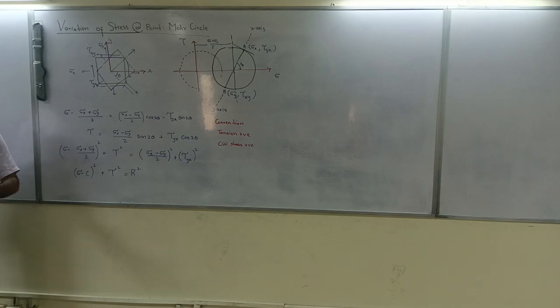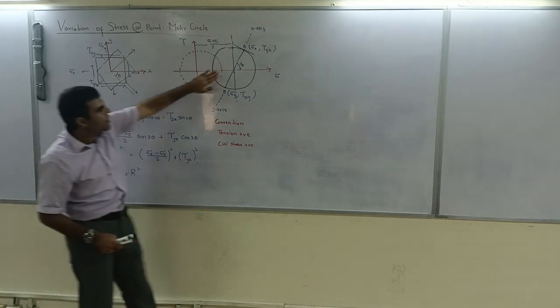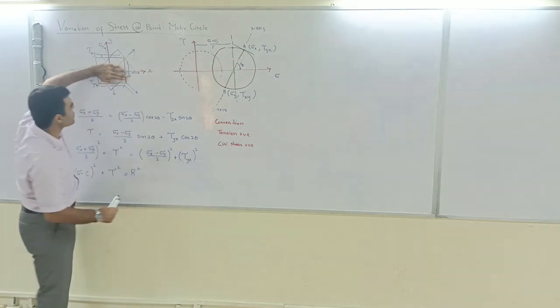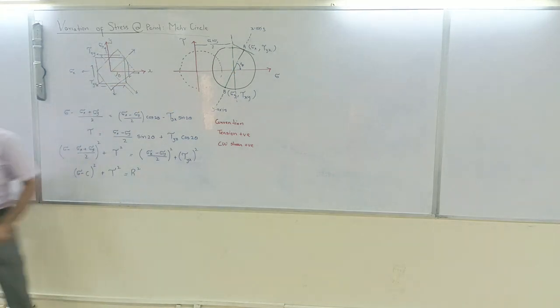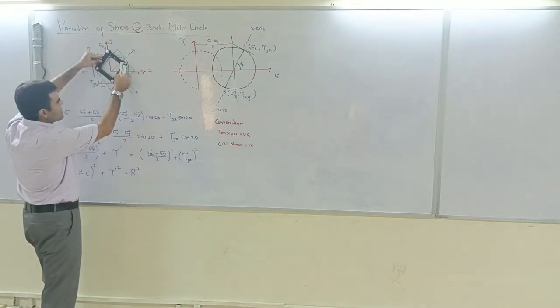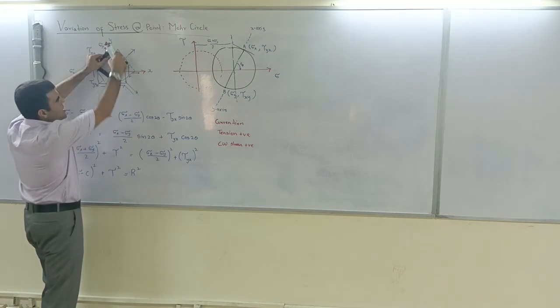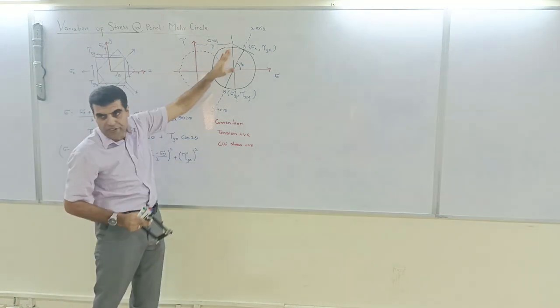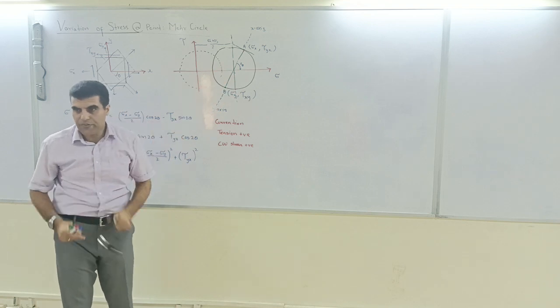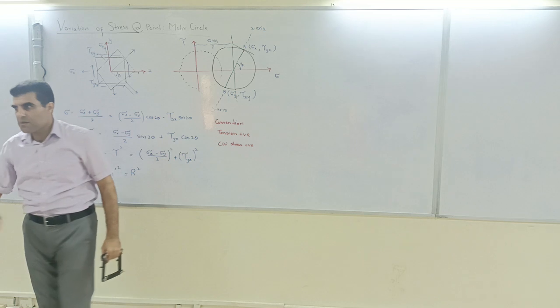If you are asked to find the plane having maximum shear stress, you then have to rotate it counterclockwise. So counterclockwise would be like this. You rotate it like that, and for that element you find all your stresses and shears corresponding to each and every face. That will be the plane of maximum shear stress.